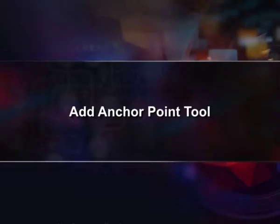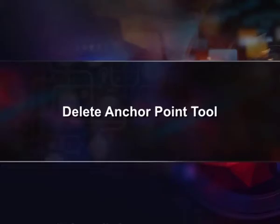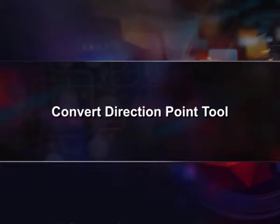Pen Tool. It creates a line between two anchor points you make. Creates straight lines if you simply click and release to make anchor points. Add Anchor Point Tool. It adds a point to a path, which is a simple way to change any path. This helps to turn one shape into another. Delete Anchor Point Tool. It deletes points from a path without causing a break in the path. Convert Direction Point Tool. It changes the control handles around an anchor point, reshaping the segments controlled by that anchor point.